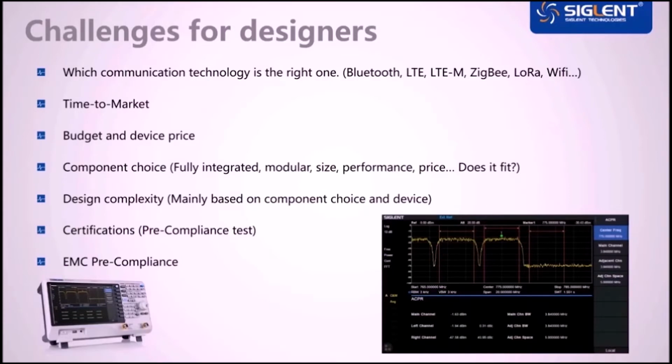Therefore, our spectrum analyzers offer ready-made measurements with which these signal properties can be easily checked. Of course, the topic EMC should also not be underestimated, especially when you use a device with a high-frequency DC-DC converter to be particularly efficient and also have antennas in your device. At this point, these antennas are a perfect way for the distortions to leave your device.